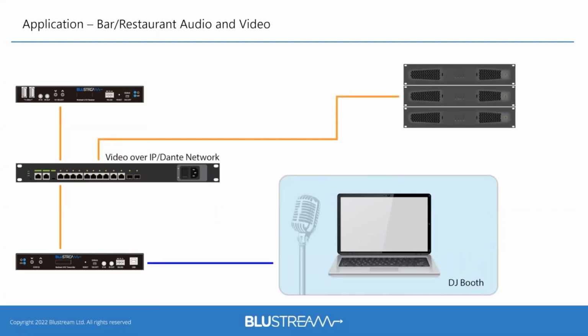When things like mics are needed, these can also be connected to the available analog inputs on an IP250. However, with Blustream, we can open additional connectivity options if, let's say, you're using an analog microphone and want to directly connect to the network to be distributed or amped. Using a DA11 AEN or Dante encoder, we can connect up to 2 individual channels or microphones that will encode and feed right into our Dante network.